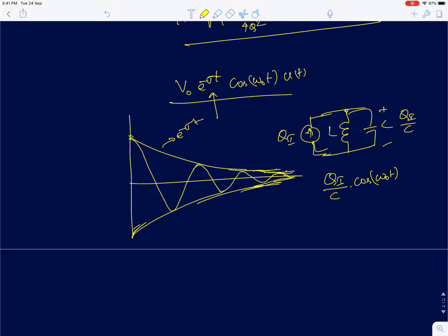It's never lost. But now in a parallel RLC circuit, every cycle some amount of energy is going to be lost in the resistor. Because it's going to be lost, the amplitude of the sine wave is going to reduce. I mean the energy in the system is going to reduce. For example, the peak energy is half C V naught square at t equal to 0 on the capacitor. Now that is going to reduce, so that can be seen as a reduction in the amplitude.